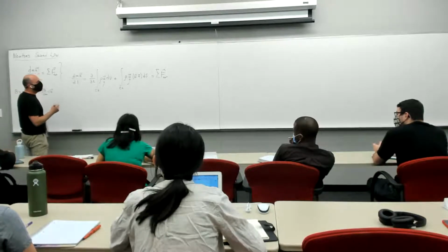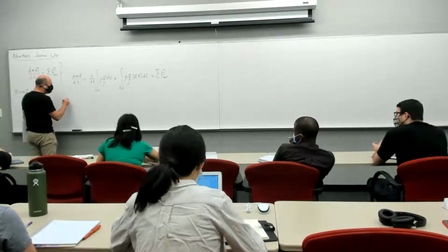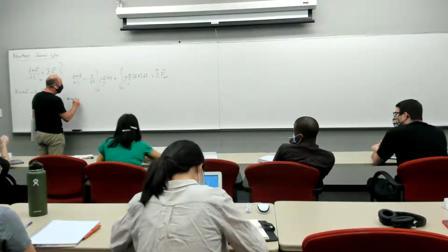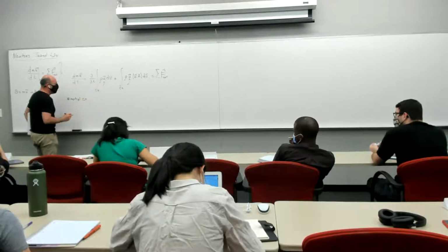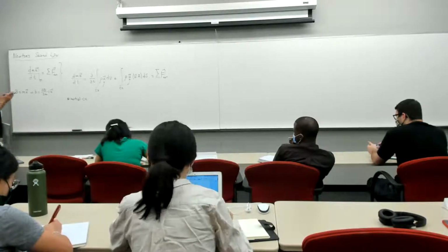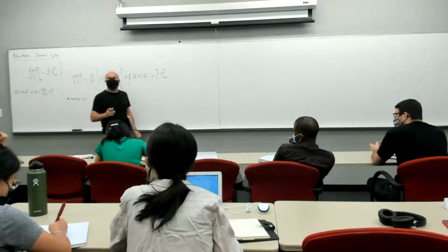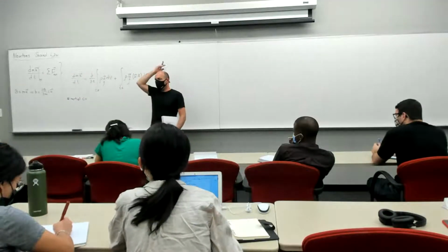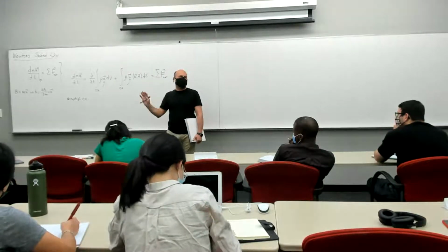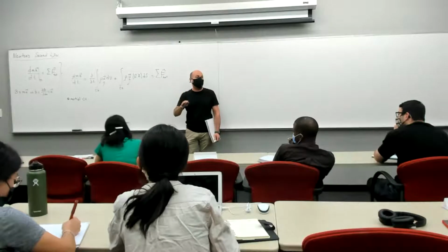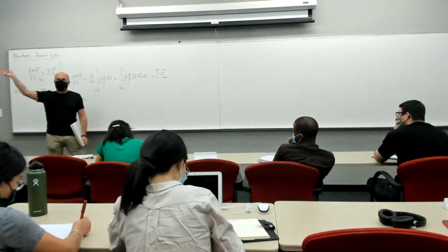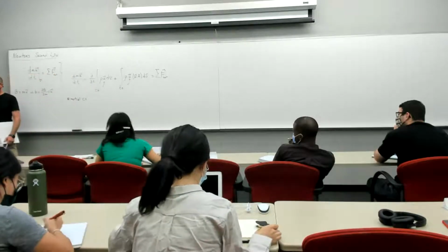Now, there's a couple of limitations here, in that this integral form applies only to an inertial control volume that is not accelerating. Okay, so if you were to apply this integral momentum form to something that's moving like a rocket motor, for example, and you have a change in the thrust and you're calculating the forces, you've got to do a few things differently. It's doable, but we're not going to worry about that because our goal is to get to the differential form. And the differential form doesn't care about whether the volume is inertial or not, okay?